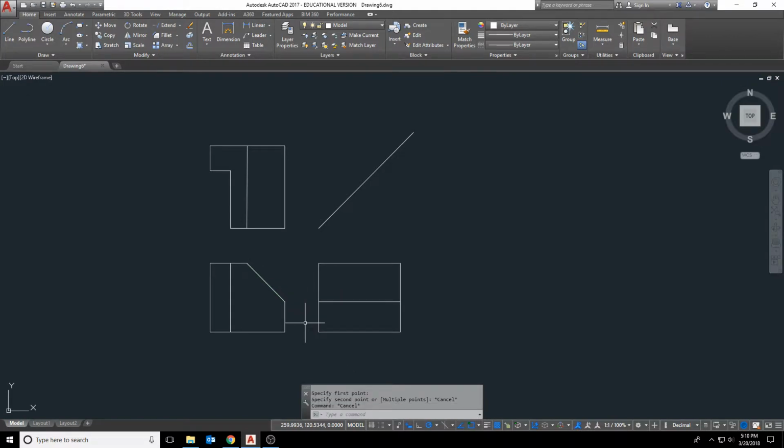So if you put it in the center, we're going to call it right, because if you put it in at 18, it's going to be slightly off center. So what I need to do, knowing that this is at a 45-degree angle, if I draw a line from this midpoint and I just come out a little bit at 45 degrees, that's basically going to locate where the center of this hole is for me.